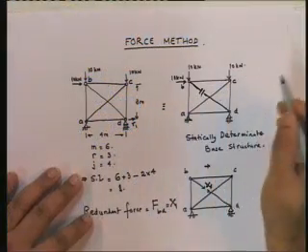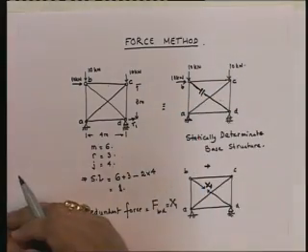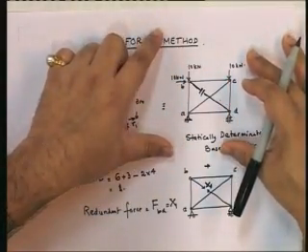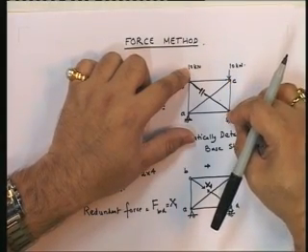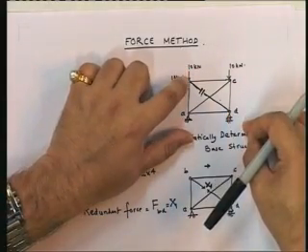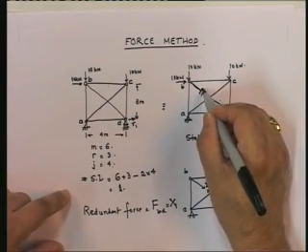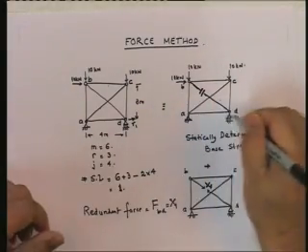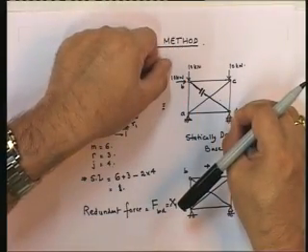Let us go back. I've made a cut here. So when I make a cut here, under the action of these forces, what's going to happen to the cut? You see, all the members, the joints will displace, the members will deform, and because of all of that, what's going to happen? If this member moves along this direction relative to this, which is bound to happen because they all move independent of each other, there is going to become a separation. There's going to be an opening or an overlap depending on how B and D move. If D moves closer to B, there will be an overlap. If D moves away from B, there's going to be an opening.